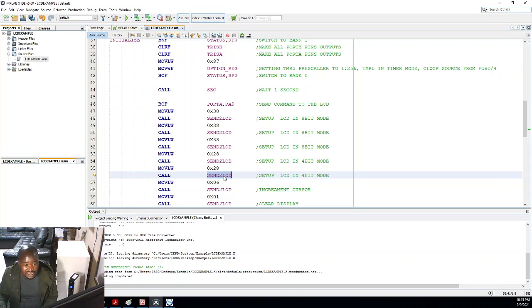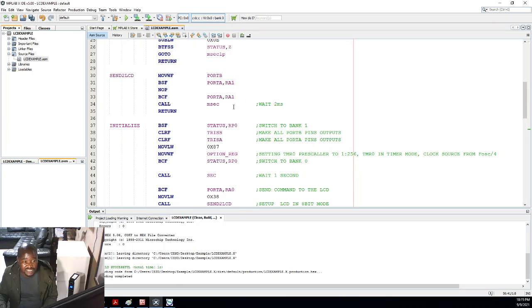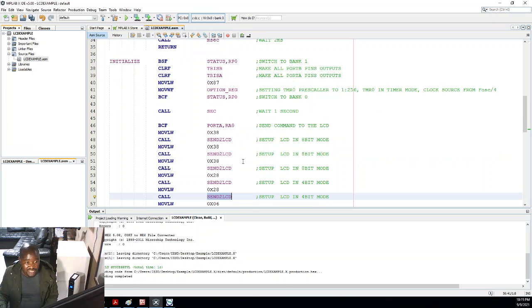We are not sending this data twice. We are still clocking it once as if it's an 8-bit. How are we supposed to send this data in blocks of 4? So basically, let's start with 8. We want to send 3 first, and then we send 8 after. When in 4-bit mode, we send the upper bits first, and we send the lower bits after.